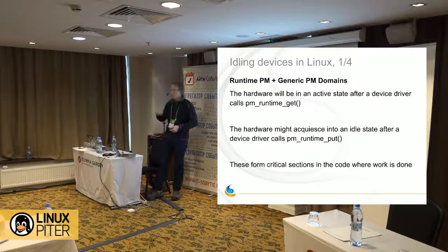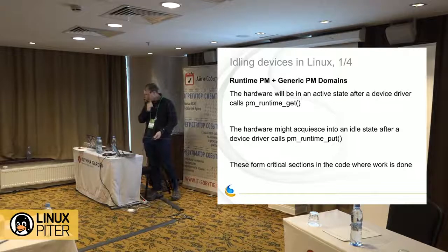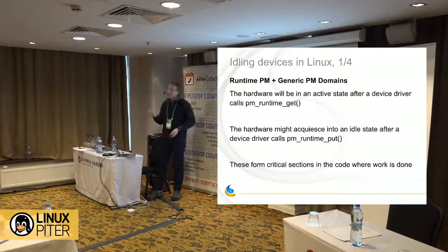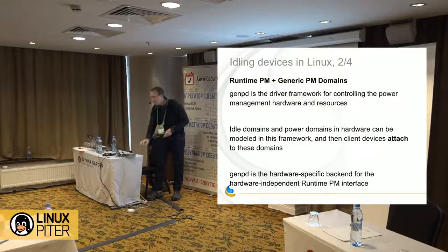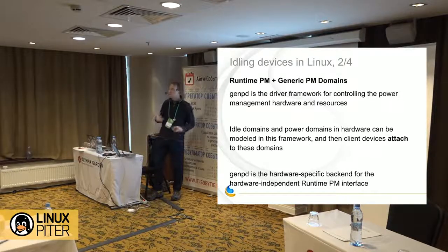Lazy developers might just call PM runtime get during module probe and maybe PM runtime put during module exit, and those people are not my friends. But on the other hand, I also sympathize with developers who maybe don't have access to the datasheet or a really deep understanding of the hardware. They may not feel comfortable trying to aggressively define very small sections of critical work. But yeah, too bad for them. Oh, and one final interesting thing is that in practice, when people speak about the subsystem, they say runtime PM, but all of the functions begin with pm underscore runtime. So when I'm grepping, I'm always mixing it up and getting it wrong.